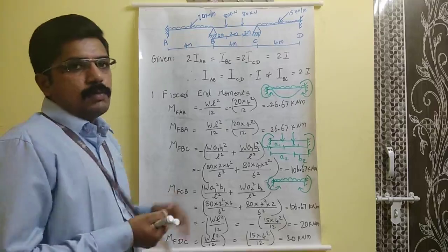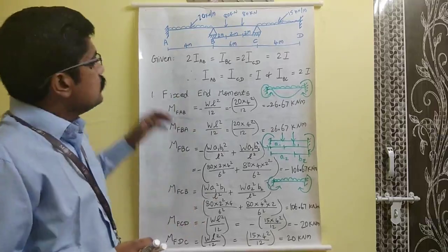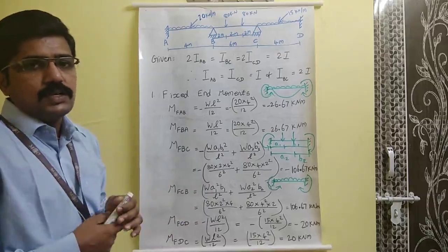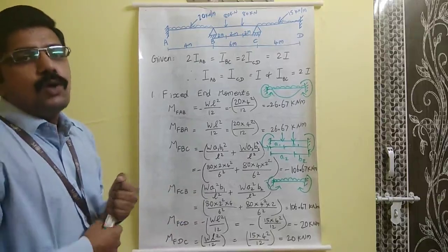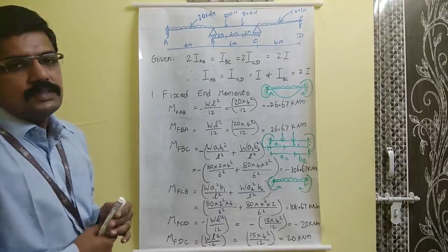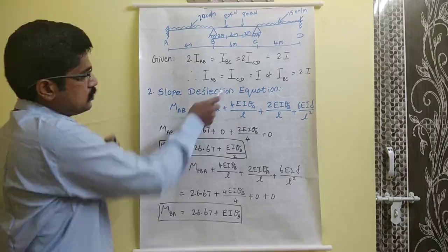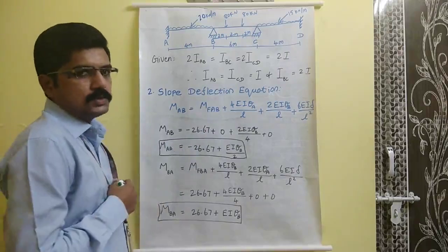While solving the problem, you will understand that concept. So this is the first step, fixed end moment. The next step is to calculate the slope deflection equation. So the second step is the slope deflection equation, where we write the slope deflection equation.